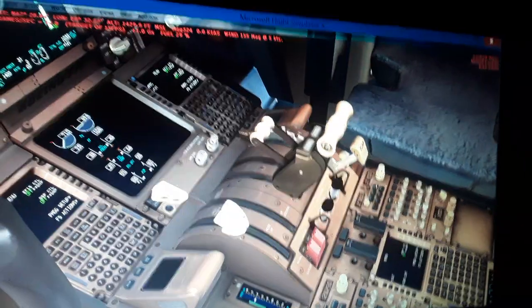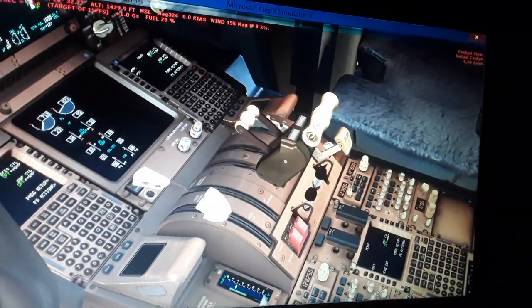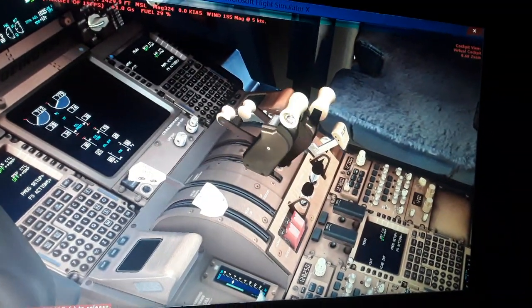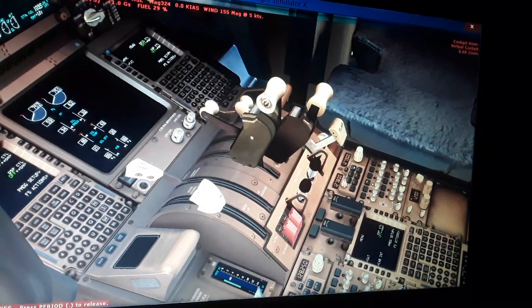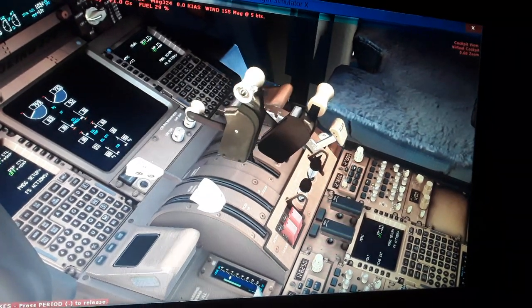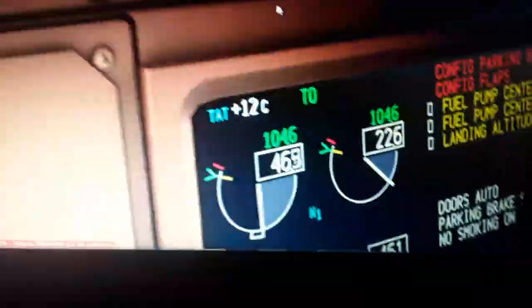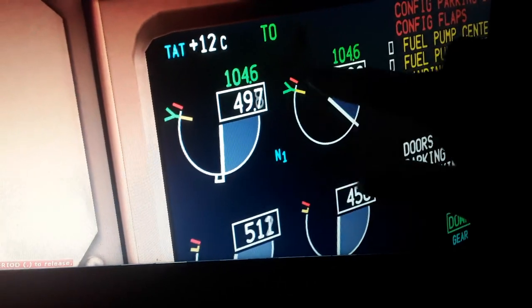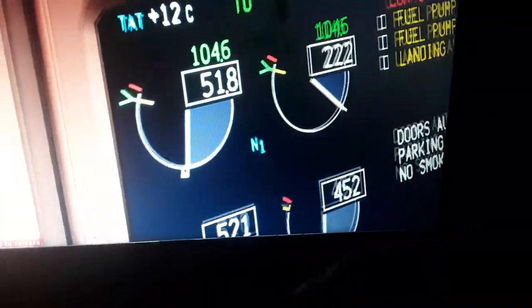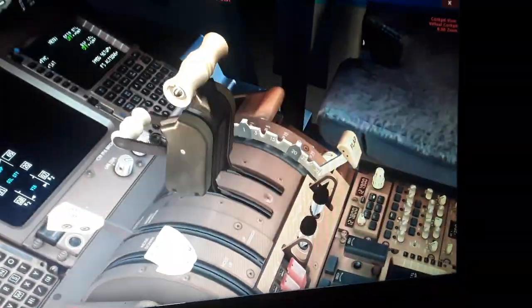So we bring both back to the same position, and also we can use the other side, the left side forward and the other side in a lesser position. You will see again the variable thrust applied like this. Here you have 50% in the left and idle thrust in the right. And just keep it increasing, and we bring both to the same position.